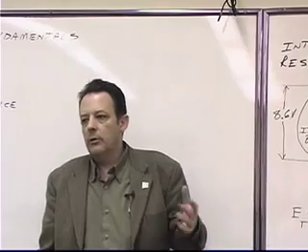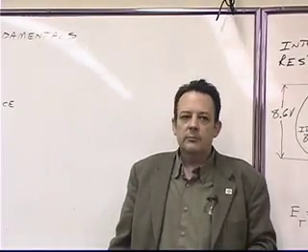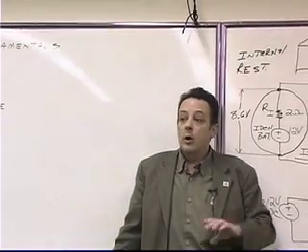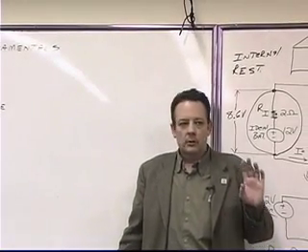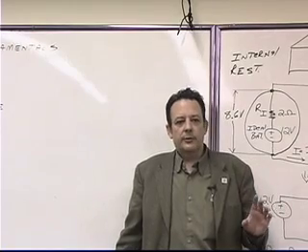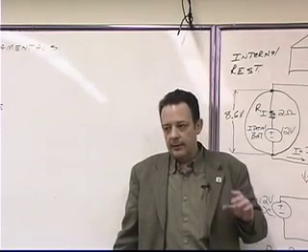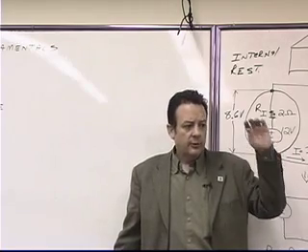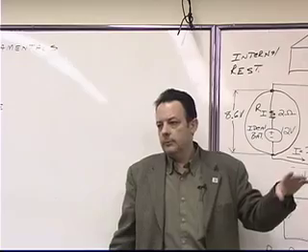There are no circuits, aside from experimental superconductors and things like that, that have no internal resistance. All sources of power have internal resistance, and that is what limits the source's ability to supply current to an unlimited load. Okay?